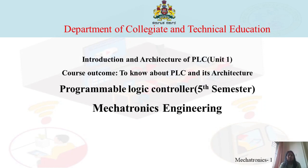After that, we have seen the working of the PLC. How it works: it executes in a scan cycle. What is scan cycle? We have three steps in the working. First, it will read or sense the input, then it will execute the logic, then it will write or update the output. This is called the scan time. So one cycle is called a scan time. It is measured in milliseconds and it happens continuously in the PLC. So it is called scan cycle.